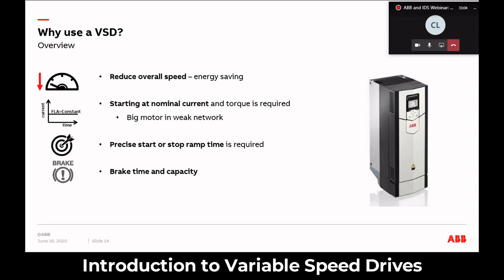In certain applications, if we take a conveyor for example, where they have to be stopped very quickly, the motor is going to act as a generator and start dumping voltage back onto the drive itself, or upstream of itself at least. The drives themselves, with one or two options, have the capability to convert that electricity back into heat and dump it onto a common DC braking system.